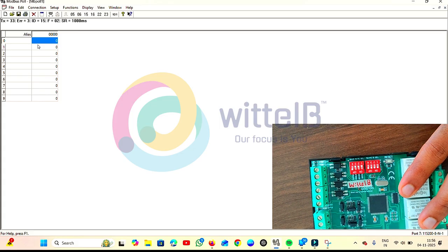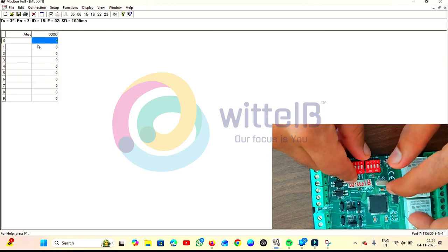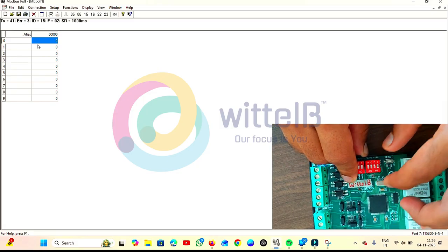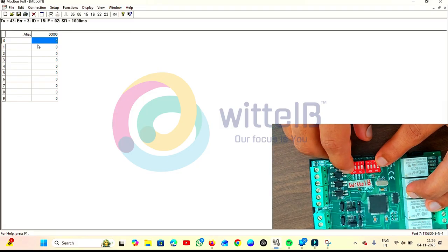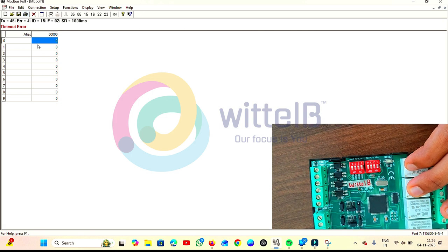Now I need to get back all these to the default. So load all the pins. Otherwise you can set only the first pin as high for the slave ID. Otherwise you can set it low. There is no issue. Now press the reset. The board has gone to the default slave ID and the baud rate.